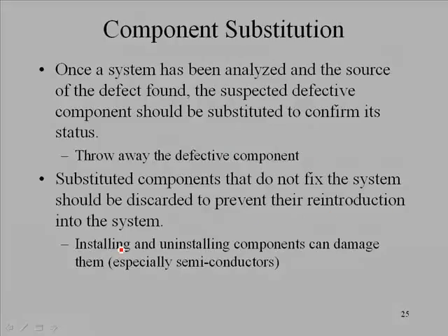And so installing and uninstalling components can damage them, even in the event that you have components that are good, you install them, then you take them out of the system. Those components should not be reused. Semiconductors are relatively inexpensive, and they can be damaged by putting them into a circuit and taking them out of the circuit, so it's better just to dispose of those and not to put those in with your known good components.